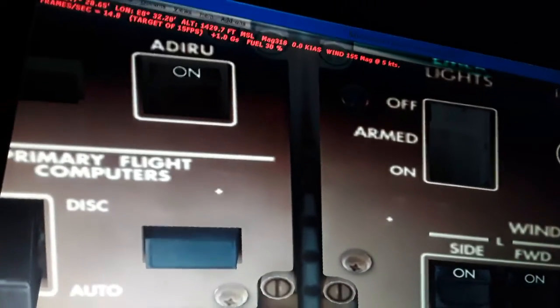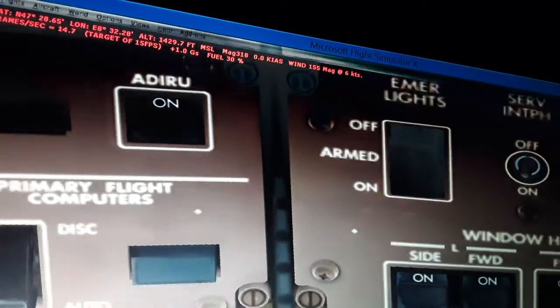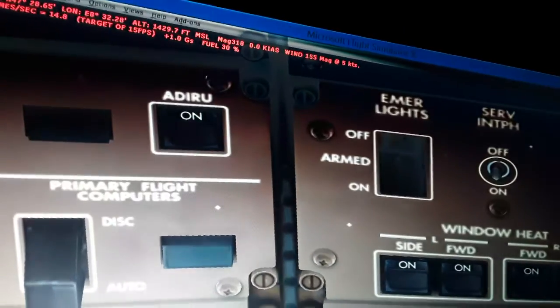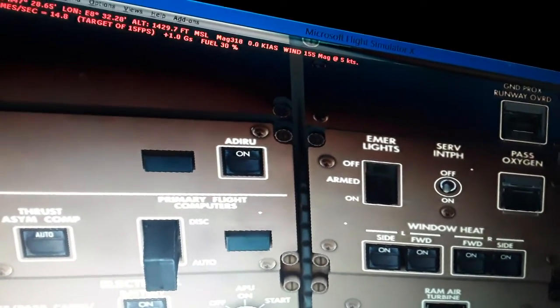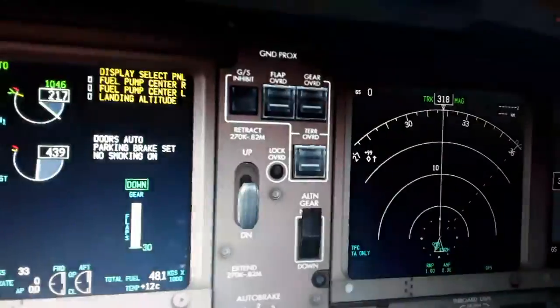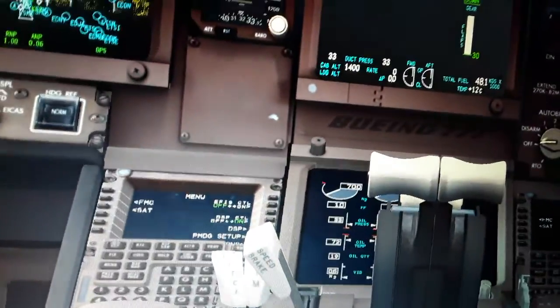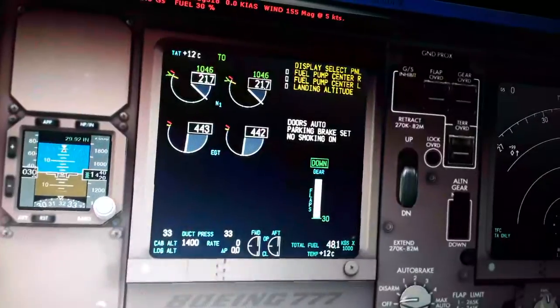What this switch, the ADIRU, is doing is it contains some systems and manages these systems. It's a kind of computer. So it's the Air Data Inertial Reference Unit. It contains 2 GPS or 3 GPS. It contains barometric and anemometric data of the aircraft using the pitot static and pitot dynamic tubes, and also contains a magnetic compass and other systems like gyroscopic acceleration and deceleration using laser gyros. And it displays this information here and here. We need to align this sometimes. The IRS, the ADIRU, Air Data Inertial Reference Unit, has different names in different aircraft models.